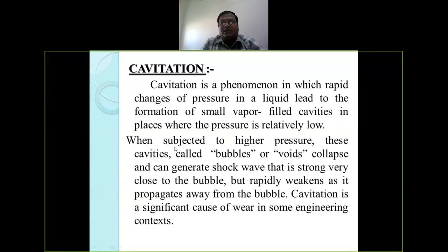Now the next topic, and the last one for today's webinar, is cavitation. What is cavitation? Cavitation is a phenomenon in which rapid changes of pressure in a liquid lead to the formation of small vapor-filled cavities in places where the pressure is relatively low. When subjected to higher pressure, what will happen? These cavities, called bubbles or voids, collapse and can generate a shock wave that is strong very close to the bubble but rapidly weakens as it propagates away from the bubble.